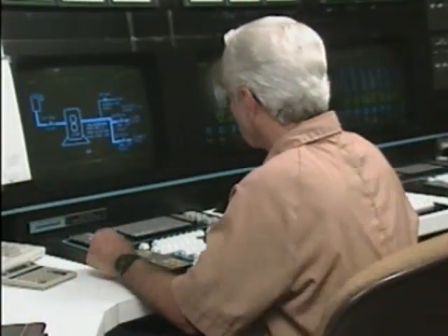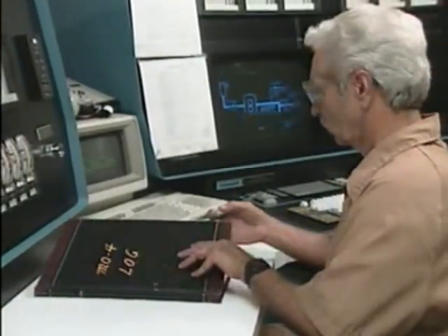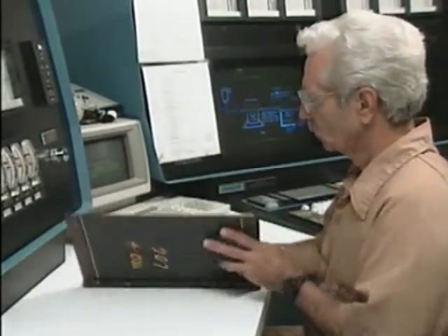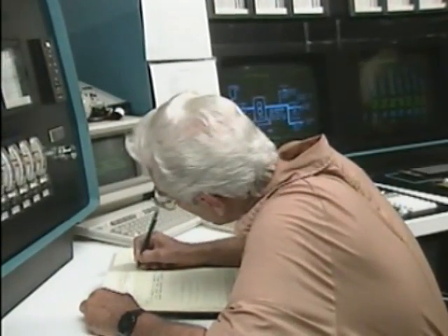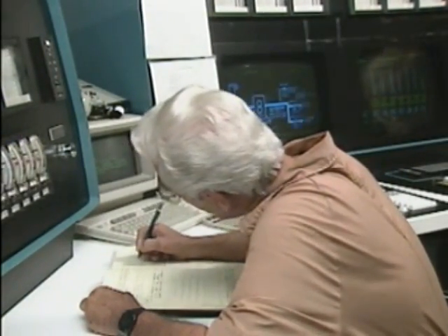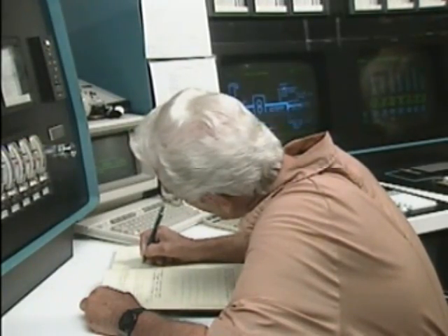One thing that can be done to help identify the causes of problems is to keep a written log describing events that occur in the process. By comparing information in the log with the information on the control charts, it's often possible to isolate the cause of a problem. Corrective action can then be taken.